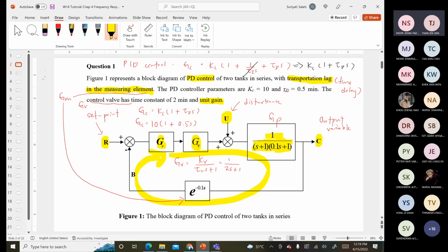And normally we just use one loop. We don't provide you two loops. It will be getting complicated. So what you need to do, you identify the loop, you count how many transfer functions are available. In this case, this is 1, this is 2, this is 3, and you have 4. So you have 4 transfer functions available in that loop.